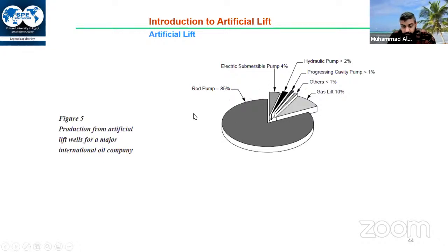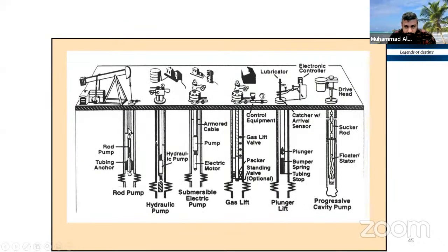And so what they do, sometimes, here's the picture. Sometimes the well does not have enough pressure to take out the oil from the reservoir to the surface. It does not have enough pressure. Could be any reason, could be bad tubing selection, could be a lot of restrictions, so it doesn't come. So what we do in this case, we have different techniques we install at the surface, the artificial lift methods through which we can take out the oil. Okay, so the most famous right now here in the States is this one. So let's look at it.